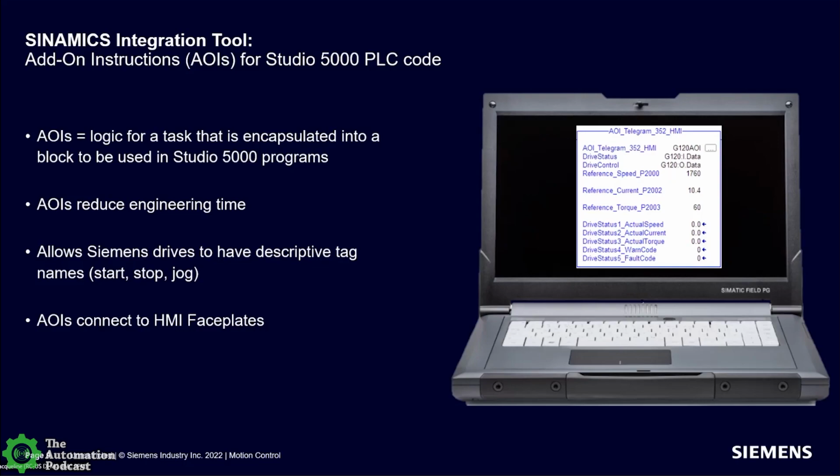One would be like positioner or speed control, and then there are more complicated telegrams. And there's also a customizable telegram, a free telegram. So it's a standard within Profinet between drives and PLCs.